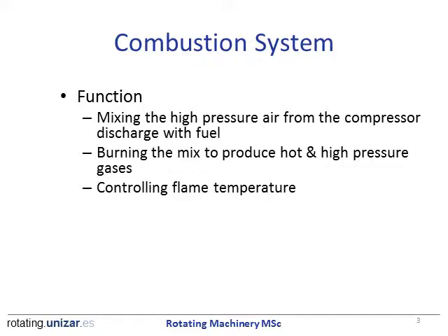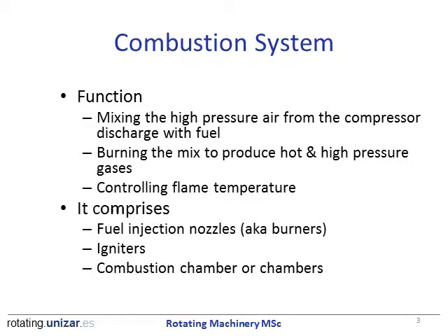And not only for the emissions, but also because the spots with very high temperature inside of the combustor usually reach temperatures that are well above the maximum limit that the metallic material will withstand. So you have to make sure that these high temperature spots don't come close to the metal walls. The elements of the combustion system are the fuel injection nozzles, also known as burners, the igniters, and the combustion chamber itself, or chambers, because it may be more than one.